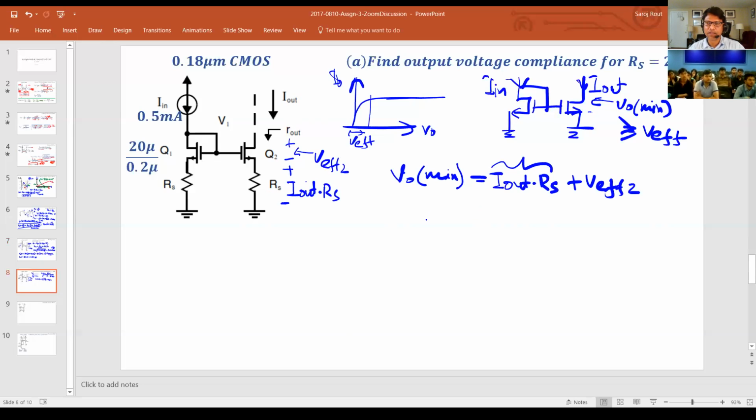So let's assume V effective is, in the previous problem, let's say we calculated 167 millivolts, right? So 0.167 volts. So for a simple current mirror, as soon as your output voltage was higher than this, you were a current mirror, and anything higher than that, you would get the same current. Well, it'll change slightly with your output impedance, but pretty much the same.